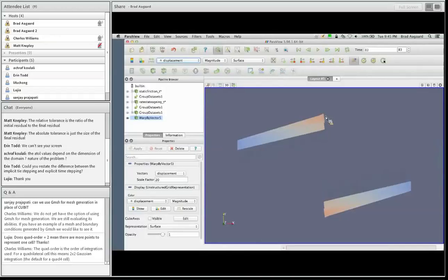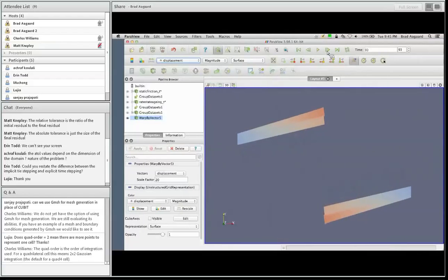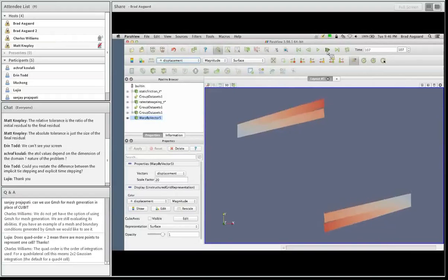You'll see that right at the end of the fault, there's a little bit of left and right motion. That's because we can't constrain the X degree of freedom right on the fault as well as the relative displacement. So remember, our node set was everything except the fault because we can't overlap the Dirichlet boundary condition with the fault boundary condition.